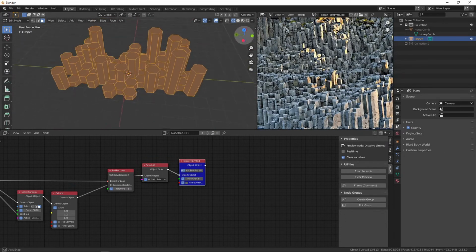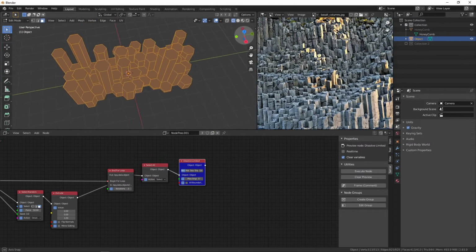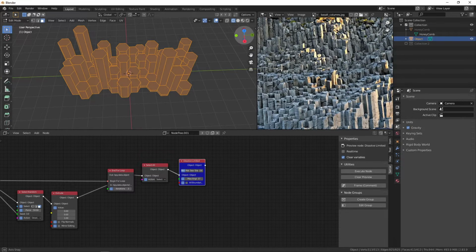And I think this is good for one of the LODs and the physics mesh. So now I'll work to create the FBX structure and parent them and create those two instances. And we'll take a look at making the main mesh the LOD0. So to start, I'll name this node graph. So it'll just be the basic one.